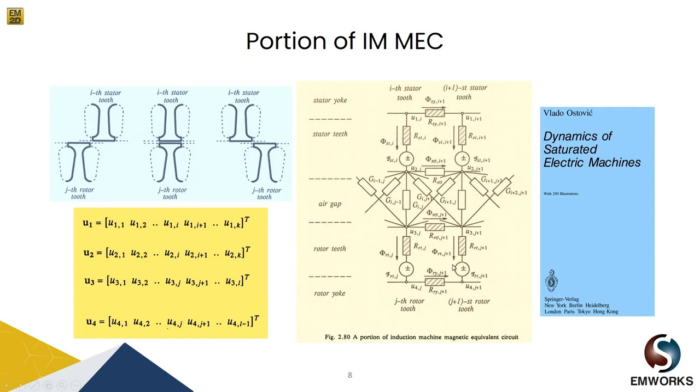So generally, we have three types of reluctances. Nonlinear reluctances due to the nonlinear property of the material, linear reluctances, constant reluctances like this one, and nonlinear reluctances due to geometrical parameters, for example, the rotor position.